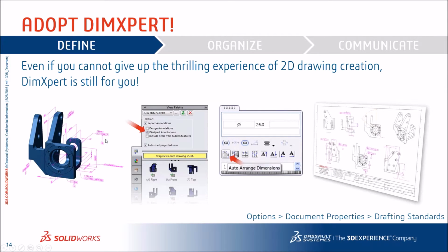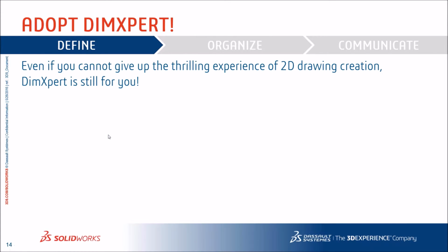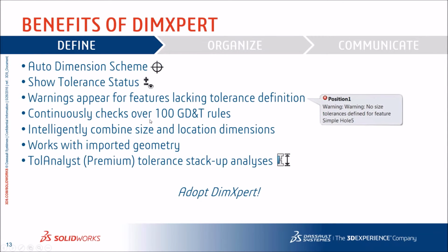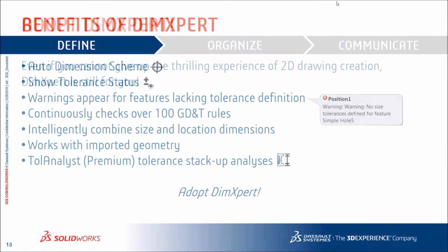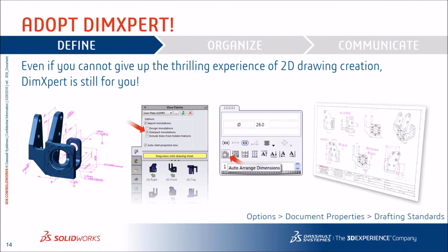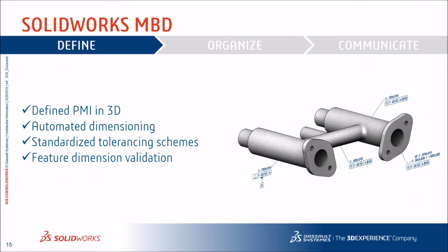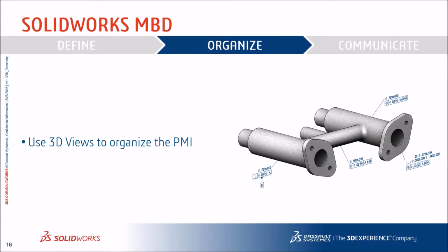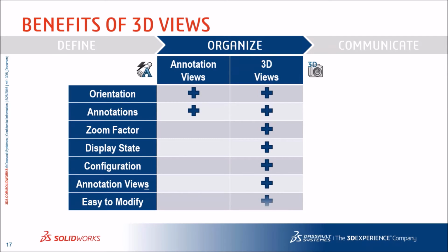What's so great about that? Well, number one, you're getting all of the benefits that I previously showed on the previous slide. But number two, when it is time to implement MBD, you do so seamlessly. You've already got the dimensions and annotations applied to the model. You're just using MBD to organize those into 3D views so that you could go ahead and make them easily consumable.